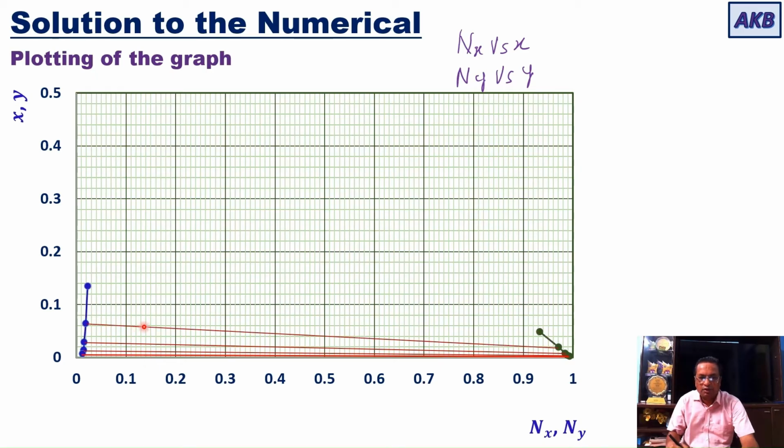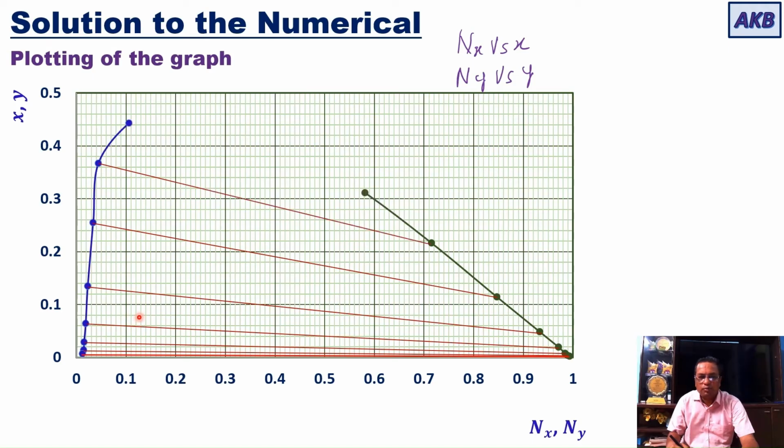So in this way, all points are plotted and corresponding points are connected by the tie line. Why? Because those are concentrations that are in equilibrium with each other. So this gives us the binodal solubility curve, and now we are going to follow the material balances on this graph. Now the first task is to locate F.